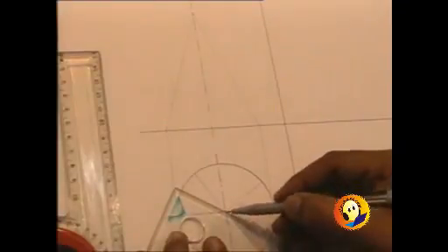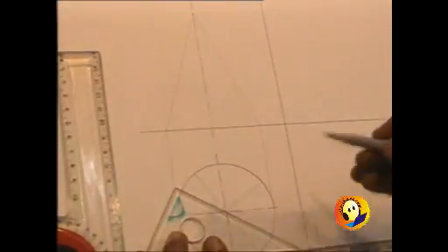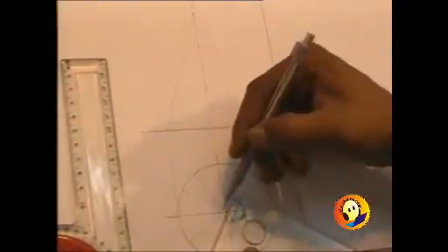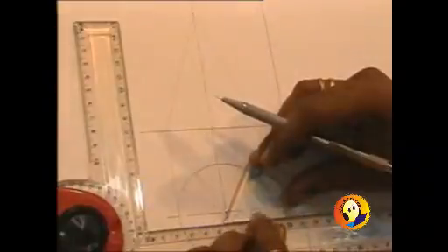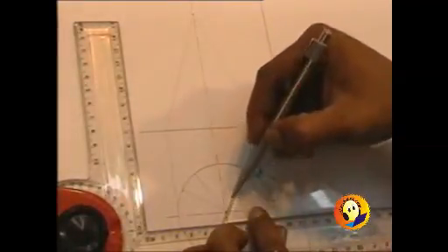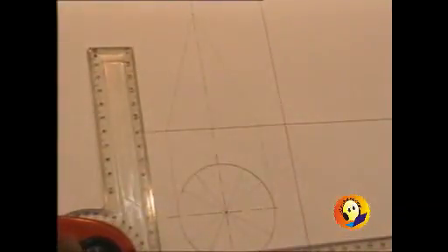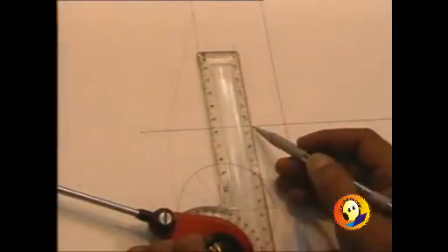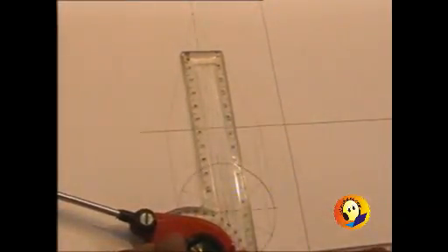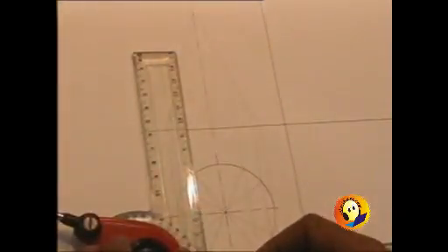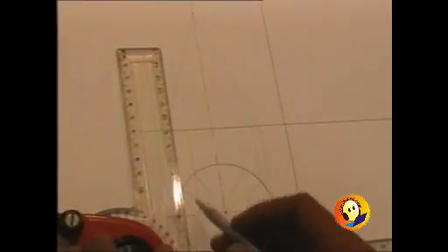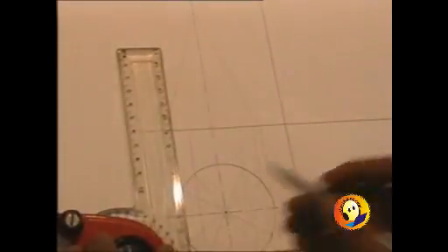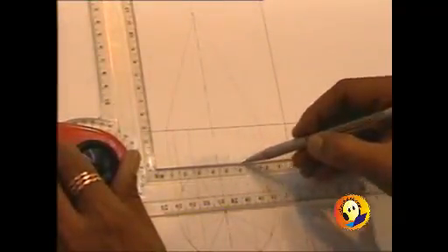So in short, when you divide it, you are required to show all those diameters which are making 30 degrees angle with each other, so that it will appear in the form of 12 points of the base which are connected to the vertex, and we will take those points up to the base of the cone, that is XY line, in front view, and the same 12 points should be taken to the side view also.